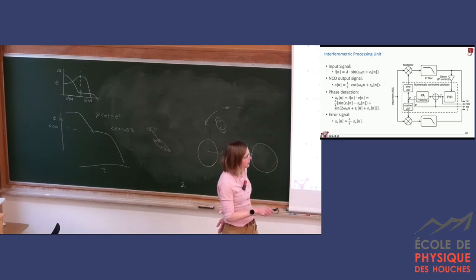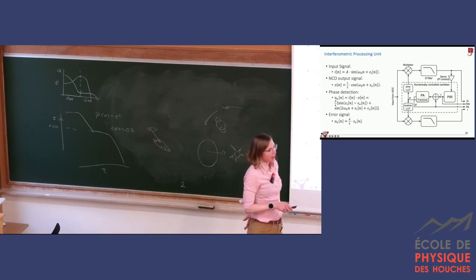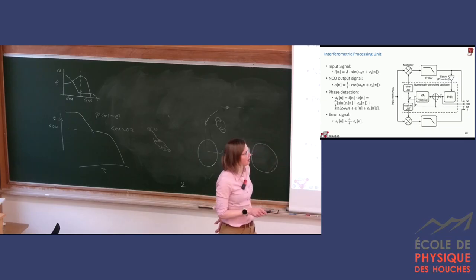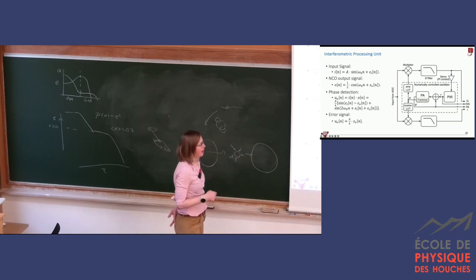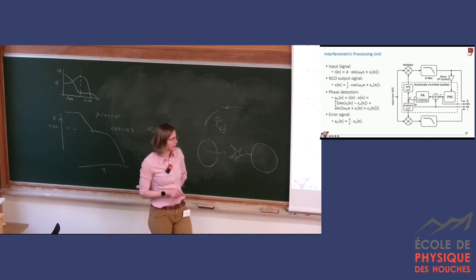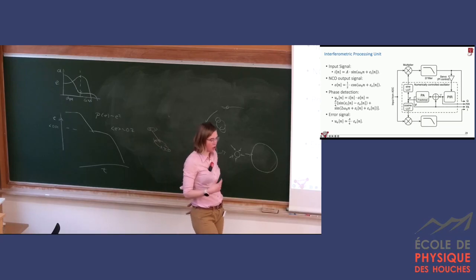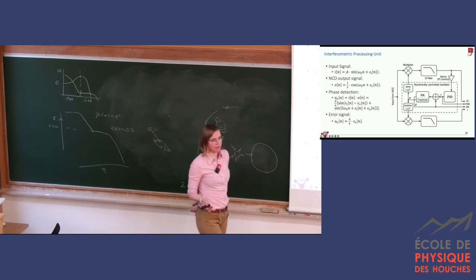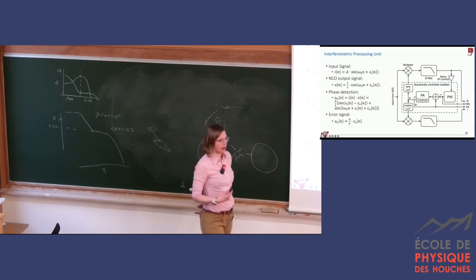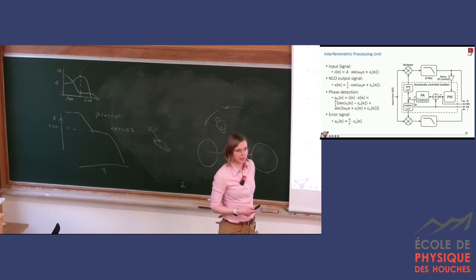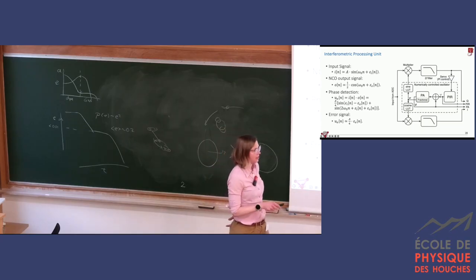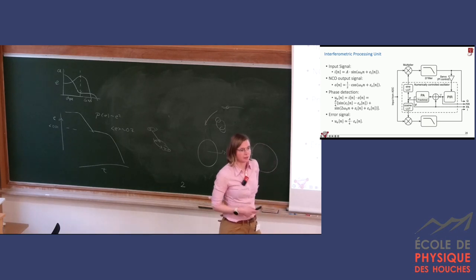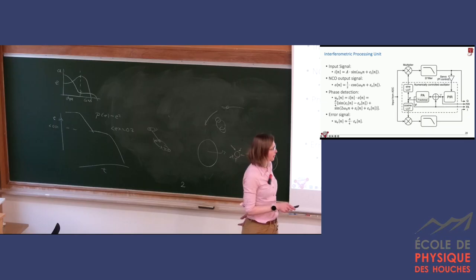Now we have also two bits sitting here. One is the phase incremental register. It takes this phase that it received, and if we think about it, we have this copy of our instantaneous phase, and if we multiply it by 1 over f, the sampling frequency, we receive directly something that is proportional to our frequency in hertz. So this is actually the signal of our scientific interest, and this is directly proportional to our frequency.